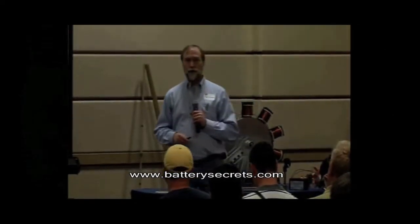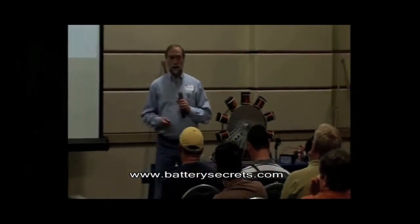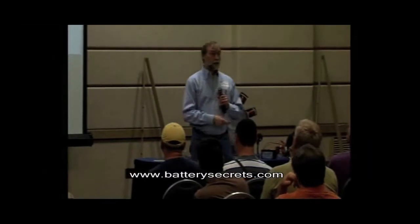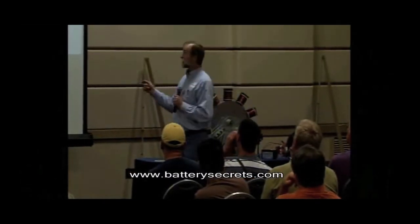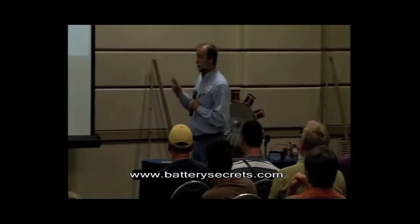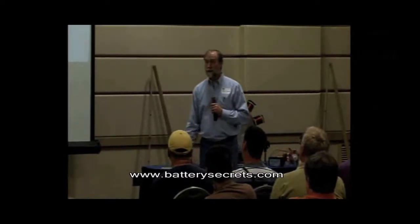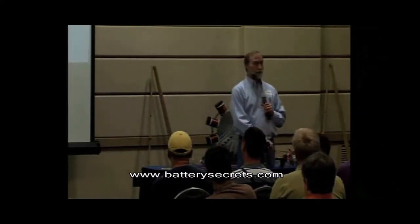If you notice what the rejuvenator machine does, it charges and then discharges. Then it charges again and then discharges a little deeper. Charges again to the top of the chemistry. Every time the rejuvenator charges, it charges to here. Then it discharges it a little deeper to challenge deeper layers of sulfation.